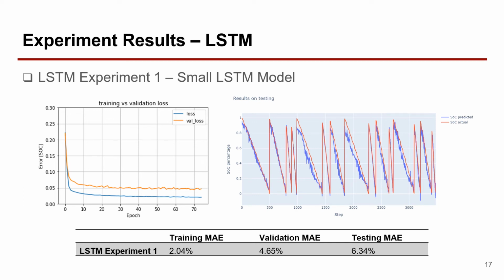The training and validation loss metrics show a significant decrease within the first 4 to 5 epochs, then lower gradually from there on. The figure below shows the predicted and actual SOC plotted together over several drive cycles between 25 degrees and -10 degrees on the test dataset. As observed along several drive cycles, the predicted SOC values are lower than the actual SOC values.